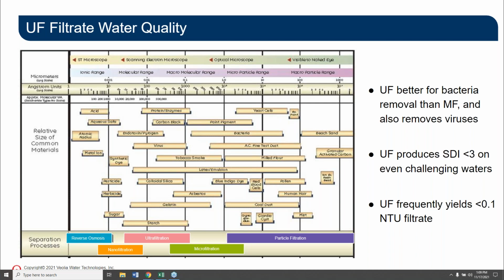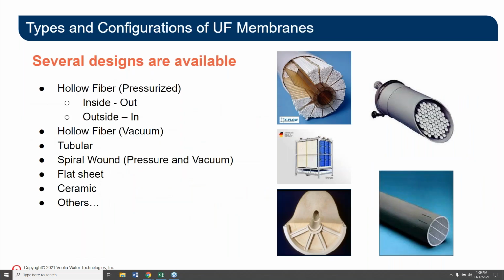So what it is really good at, when we look at running downstream processes, is that we can clean this water and filter it to a level that it can be processed a multitude of ways. It's regularly used in treating wastewater in the food industry, for concentrating proteins or separating oil and water emulsions, even removing pathogens from foodstuffs. But we use it a lot, and one of the things we're here to talk about today is ahead of RO to extend the lifespan and reduce the fouling.